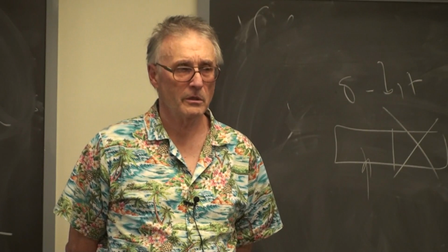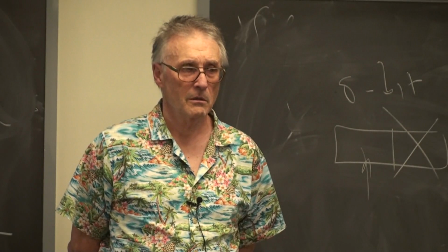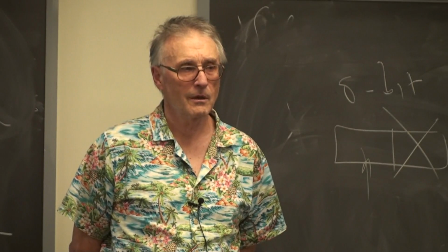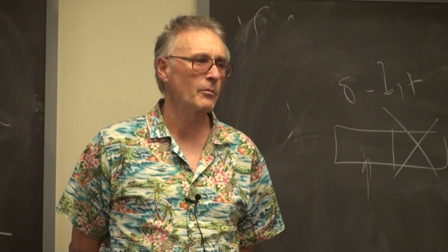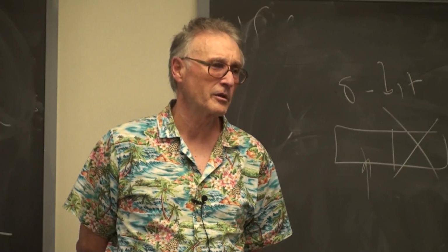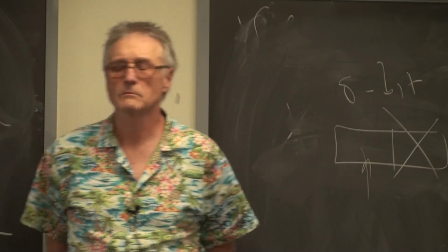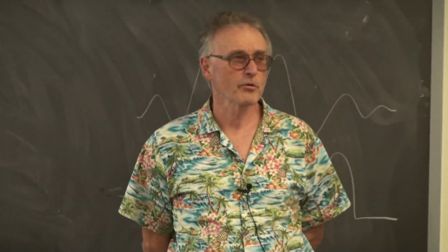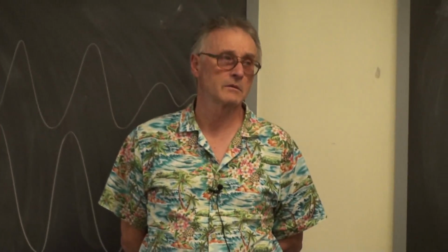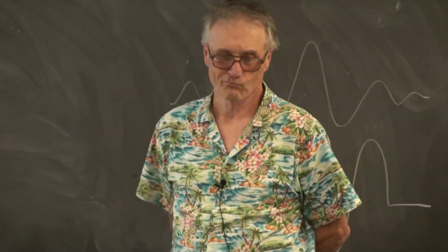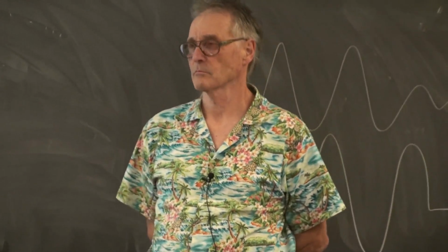How did you measure it? Using a scope, I think. And what's the input impedance of the scope? I'm not sure. Aha! 1 megohm. Okay. So if it's 100 k ohm, you're going to lose 10%. Right. You can flip the probe to 10 megs. Okay. What else?